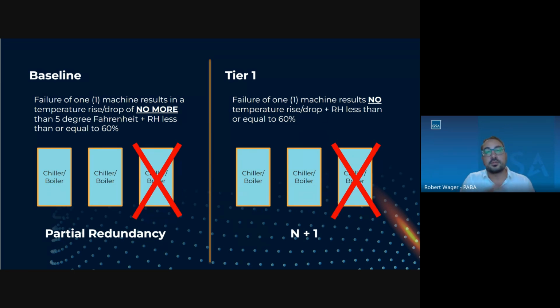And if you're opting to pursue tier 1, that's a little bit easier because you'll show, hey, I have 2 machines that are designed to capture the peak demand of the building. I have 1 machine on standby. It's an N+1 criteria. So that would be what we look to see. So that was my final point on that slide. If anyone had a question, I'll be happy to answer it now.